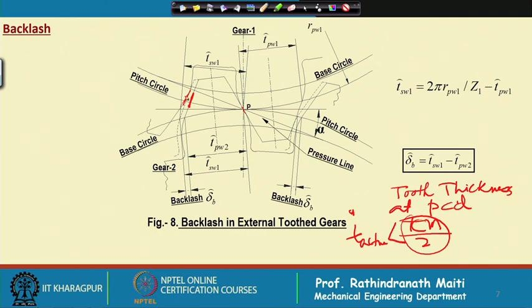However, where we are changing the center distance, then these calculations come over the amount of corrections, and normally we need not calculate such backlash and then calculate the depth of cut. Usually this automatic setting is there, or maybe if we cut twice or thrice on the same diameter, then automatically this gap will be generated. However, this is a different issue.